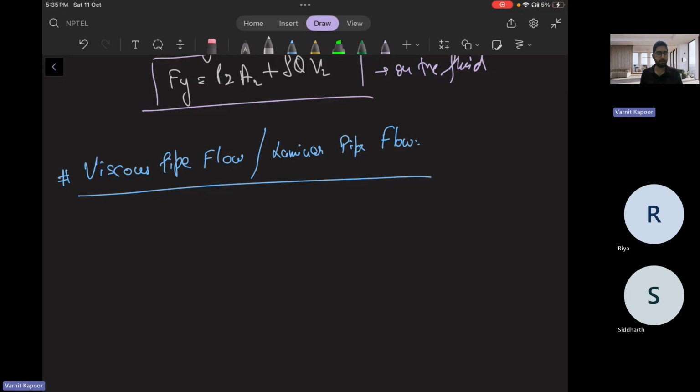So what are the features of a laminar flow? There is no slip at the surface, that is, the velocity profile approaches zero at the surface. But in turbulent flow, the velocity profile approaches up to some laminar sublayer thickness, and it forms a linear profile.